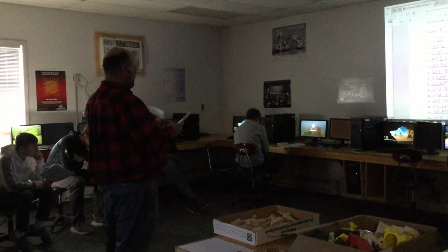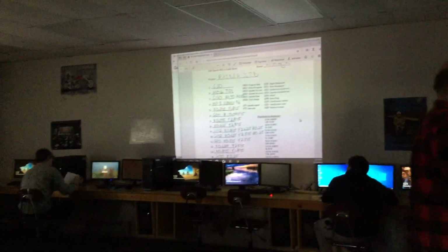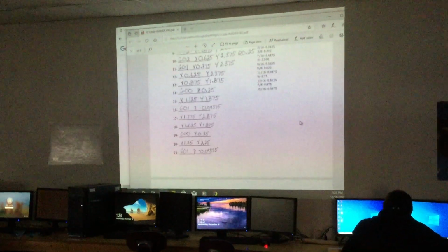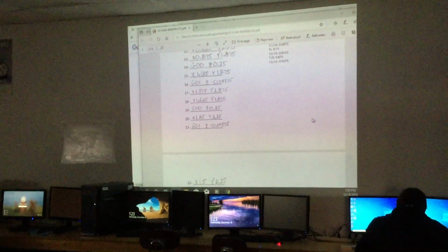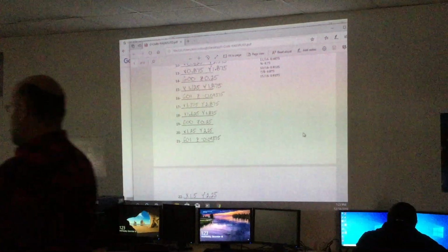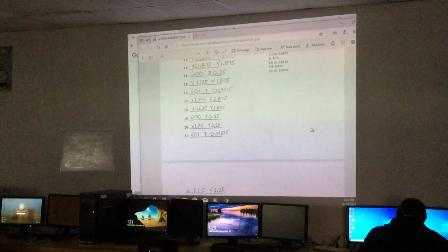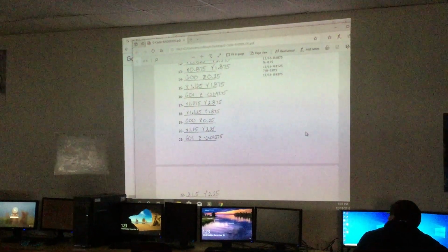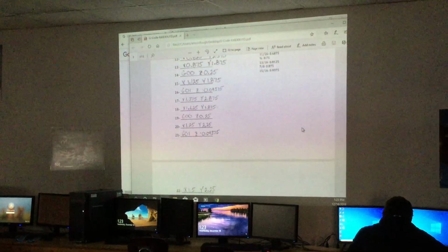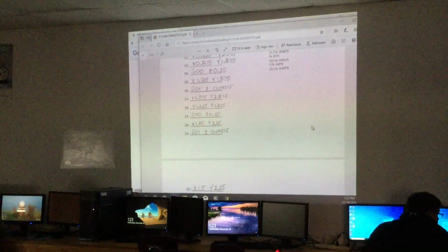So then after 13, let's scroll this up a little bit. At 13, I finished what letter? The point R. The R. I finished the R, okay? So then what do I want to do with Z? So in step 14, what did I do? Up. And I did rapid movement, and I moved the Z up just a quarter. So that means it's a quarter above the workpiece.